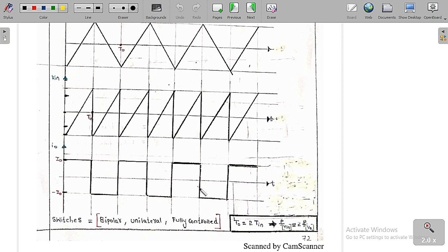So whenever the current is a constant, what are you going to get? Whenever the current is a constant, voltage is equal to the integration of the current. So simply we can say that we are going to get a straight line. It's like a ramp signal; for the integration of a DC signal we are going to get a ramp signal.